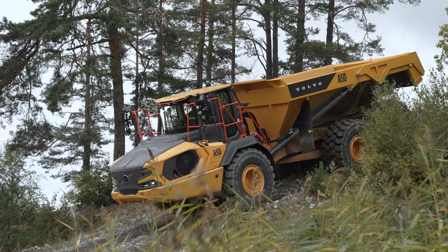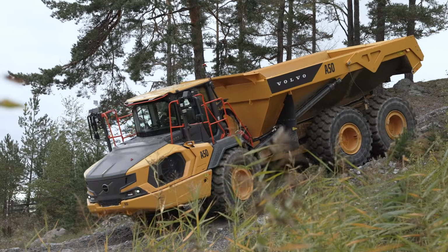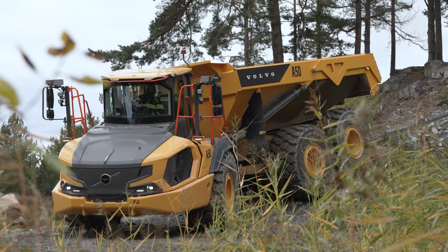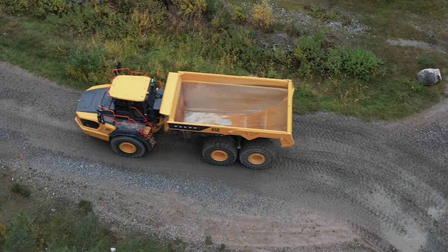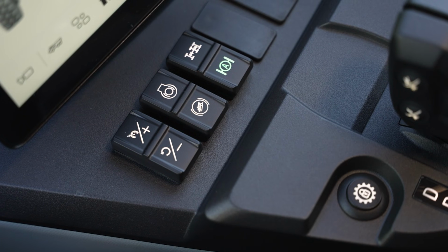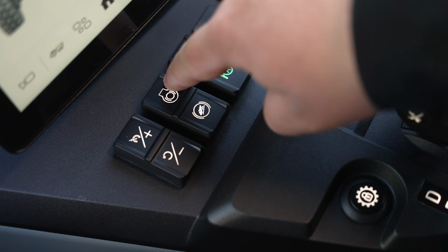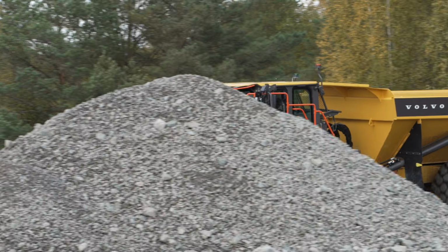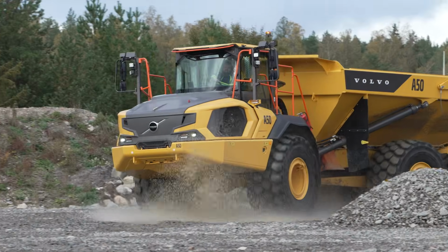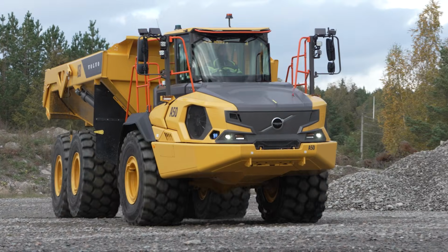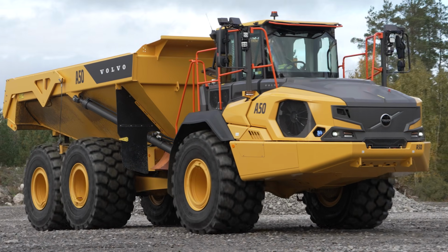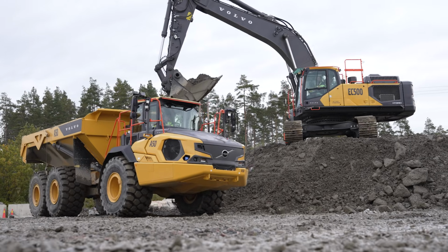Volvo articulated haulers have retardation systems, which provide speed control during the whole work cycle. For example, when operating downhill and when slowing down before curves. The Volvo engine brake is activated with a switch on the instrument panel to allow continuous use of the engine brake. When activated, it is automatically applied when the throttle pedal is released.